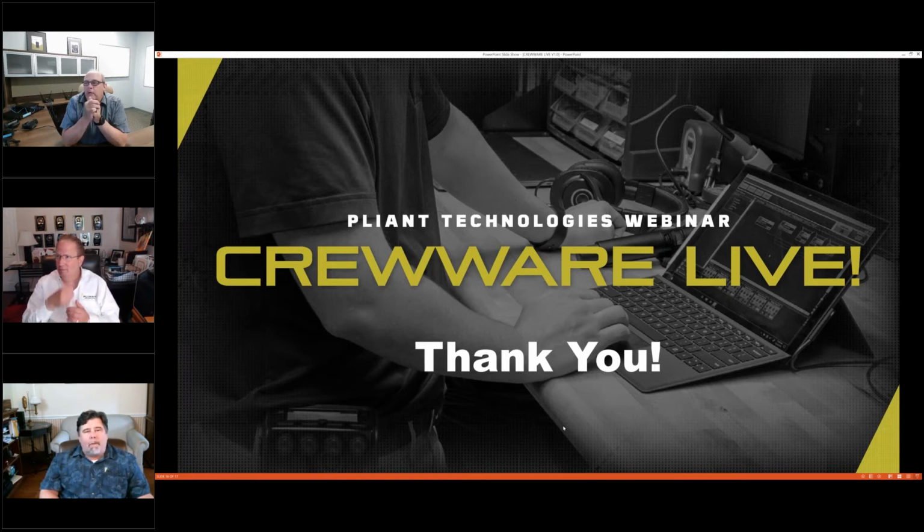And I'll add on to that real quick. We didn't really point out, but on the back of the control unit, there's a sync input. Now it's an input only. And I made this mistake early on when we saw the system, where you would connect up the two sync ports. That's not how it works. You take a CrewNet port anywhere on the system and plug that into the sync input.